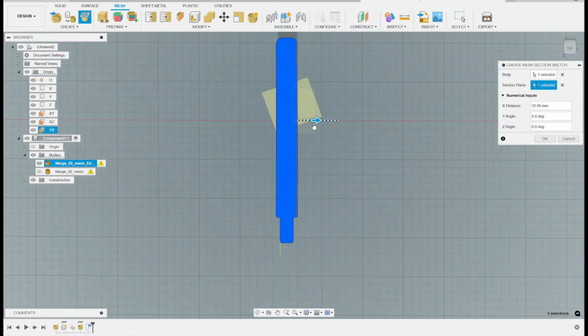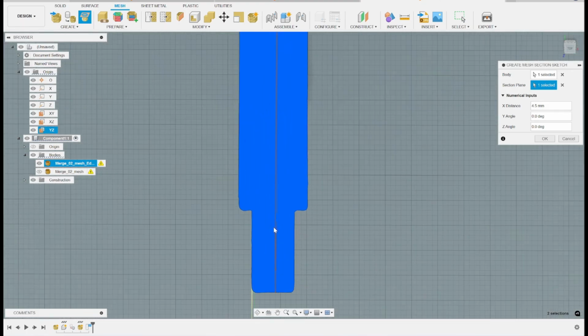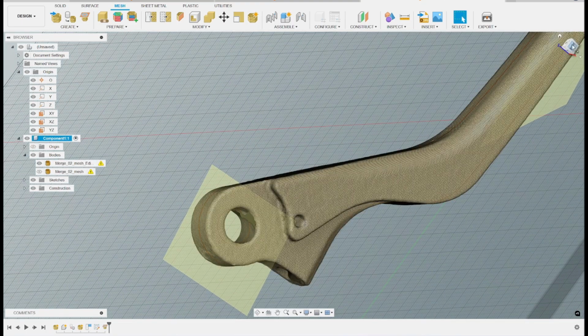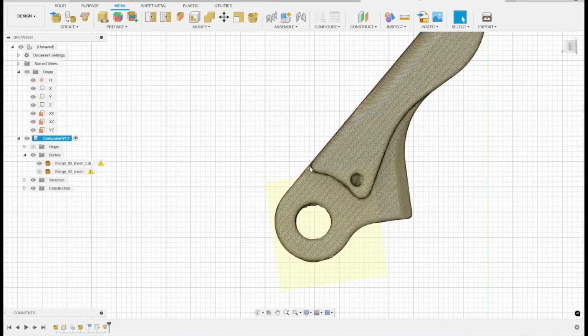Now drag this to about center. With Fusion, it snaps, as you can see the distance over here. So it's 5 increments. This looks like about 450. So you just type that in. Might be a little bit less, let's say 425. That looks good. You click OK. And right now it just gives you an outline.